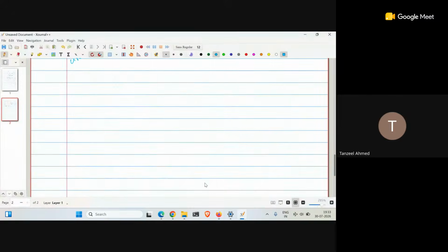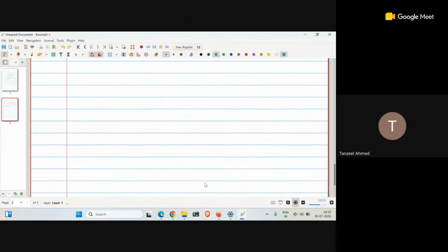So normally when we are giving this clock input to our counter, this is our clock. It's a square wave signal. It goes from low to high to low to high periodically. One cycle of the clock means it has both the high part and the low part. This is one clock cycle. You can see one clock cycle has two edges, one rising edge and one falling edge. And this has to be given into the CLK input, control input of the 163.